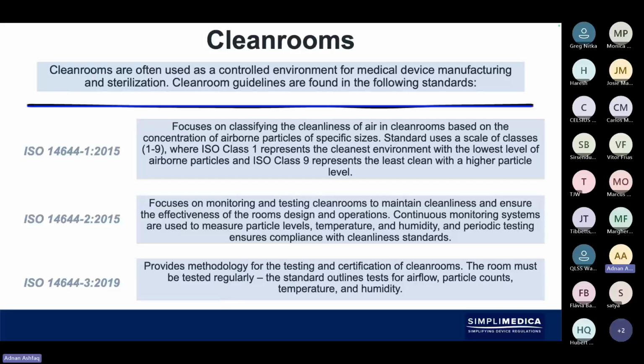So ISO 14644-1, -2, and -3, these are the standards that you need to have a look at. What type of clean room or controlled room are you packaging in? Or maybe at this point you have not even decided, but you need to decide based on the cleanliness that's required for the device that you might be developing at this stage. And there's often the question, how clean is clean? You need to look at the risks of what cleanliness you need to achieve.